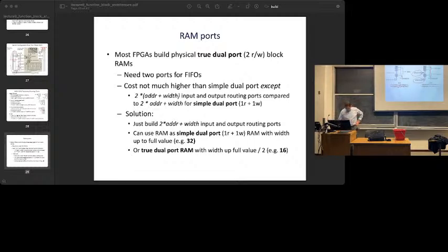We could check the same thing for what if we just use it in 5-LUT mode, like fractured mode. It's not much different. 5 read addresses, 5 write addresses, 2 write data inputs. We need 12 routing ports. We only have 6 in Xilinx, 8 in Intel. Doesn't look good. Okay, so yeah, it doesn't look like a good choice, yet both Xilinx and Intel actually have LUT RAM. So what did they do? Am I just an idiot and I can't count, or I lied to you? Routing ports are actually free. What do you think?